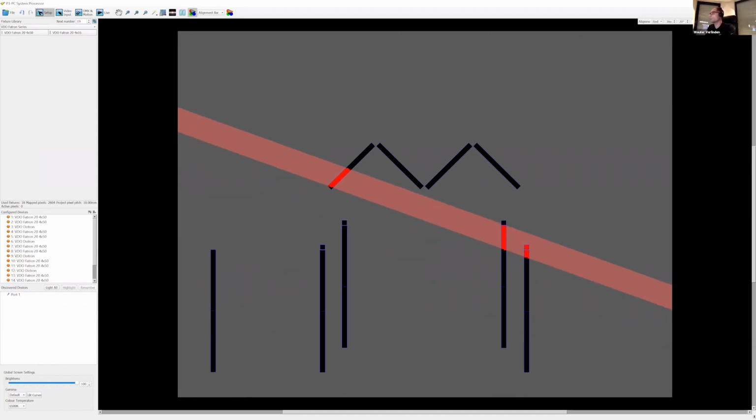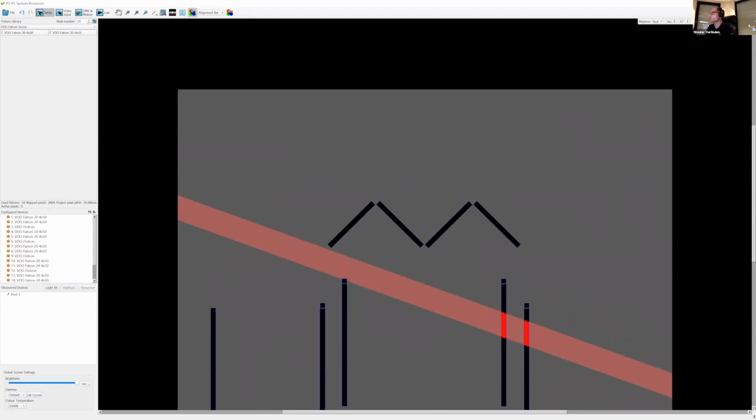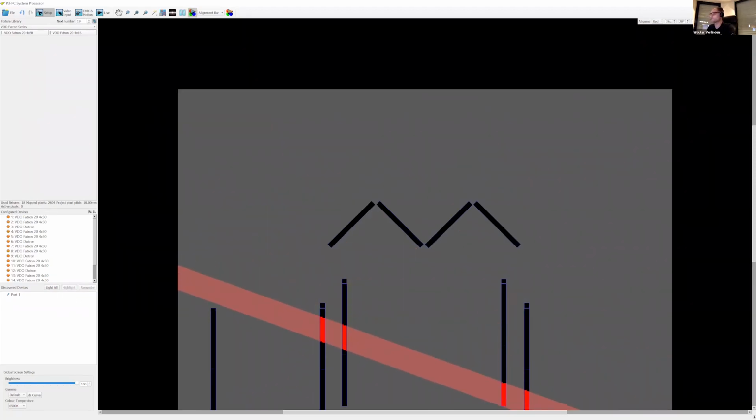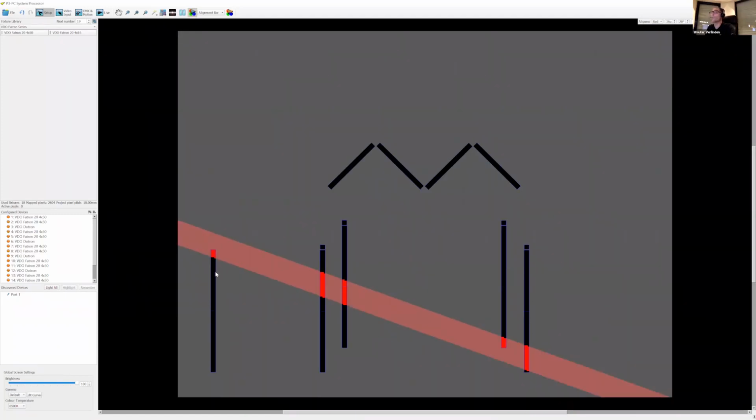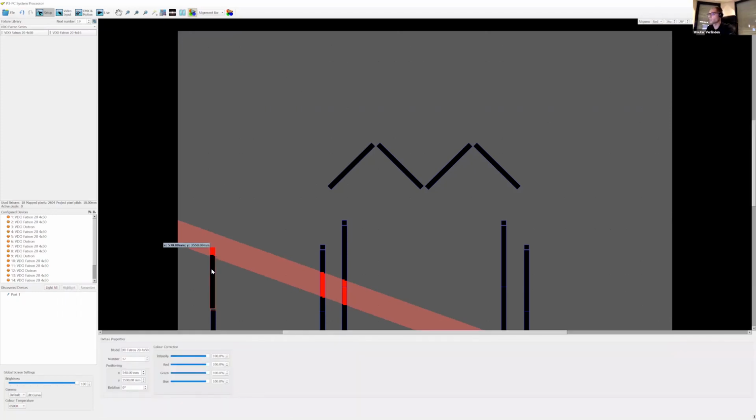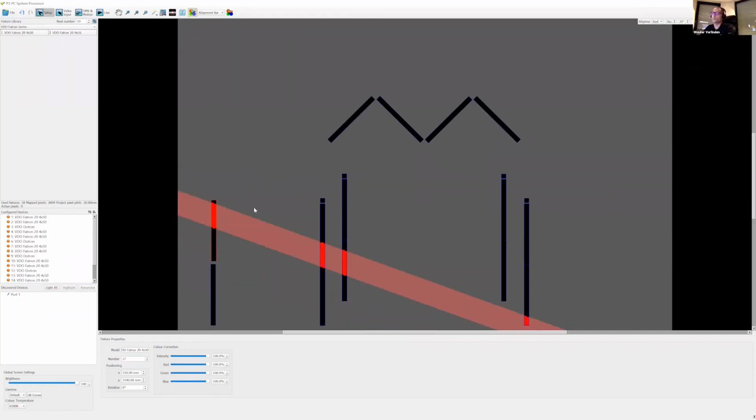So I can see, hey, this one is not hitting perfectly. And then I can, for example, here, let's just drag it there a little bit. I can, in real time, while looking at the fixture, see that the line is not hitting perfectly. So at the same time, I can do fine tuning of my mapping and then move the alignment bar a bit further. So I can just step by step work through my mapping and see what's going on in the P3 and look at the fixtures and see that also in the real world, it all maps out as you want.